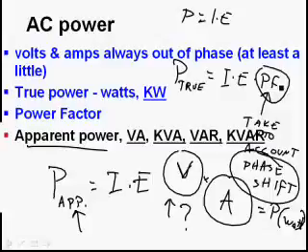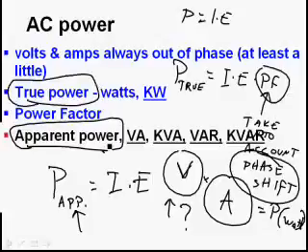So understanding the difference between apparent power and true power is a really good idea if you're going to be a pilot flying an aircraft with alternating current power. Hey, that's large turboprops, large turbine helicopters, large business jets, and transport category jets. Because apparent power is going to be what a voltmeter and an ammeter might be displaying, but true power is what you really need to know.